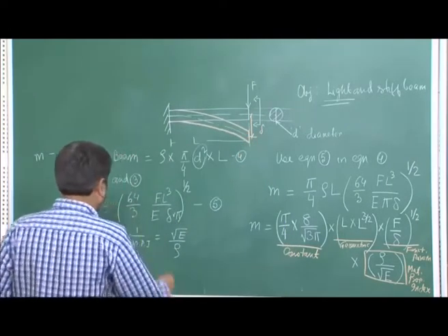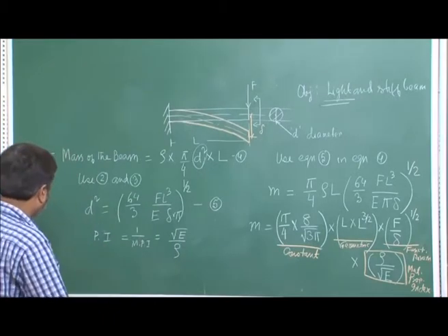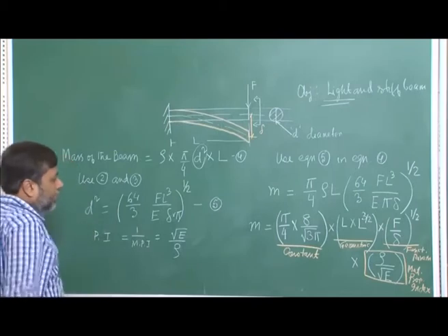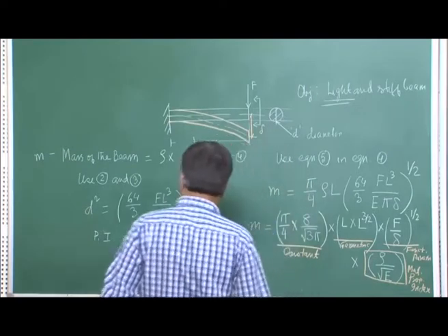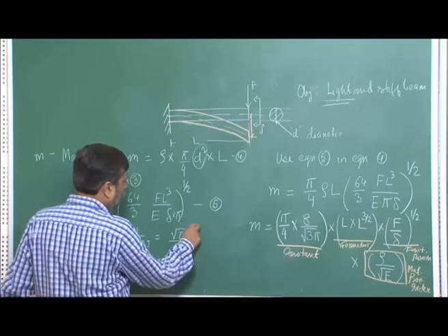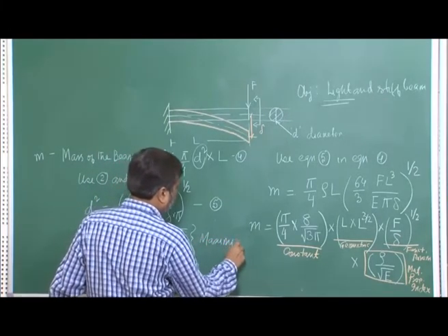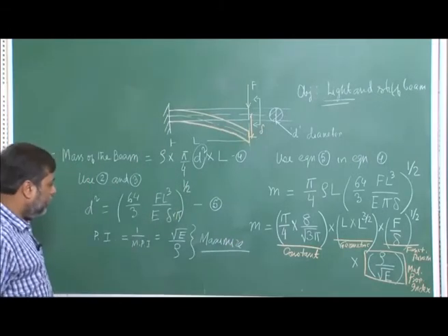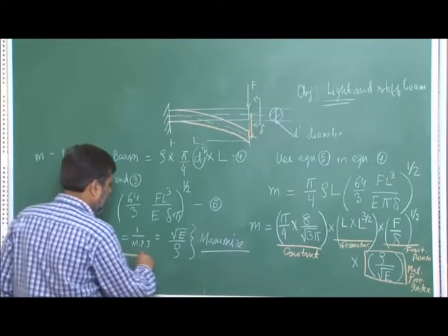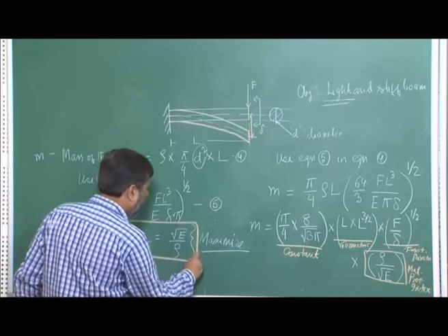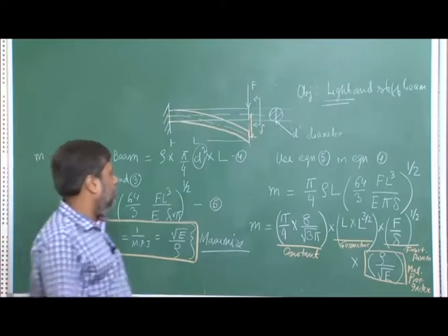That is why the E term is already here. From all the solutions, if I want the minimum mass, I have to minimize rho over square root of E, and that means I have to maximize this term. So, maximization of this performance index, square root of E over rho, is what can give us the solution. That is one thing that is clear to us.